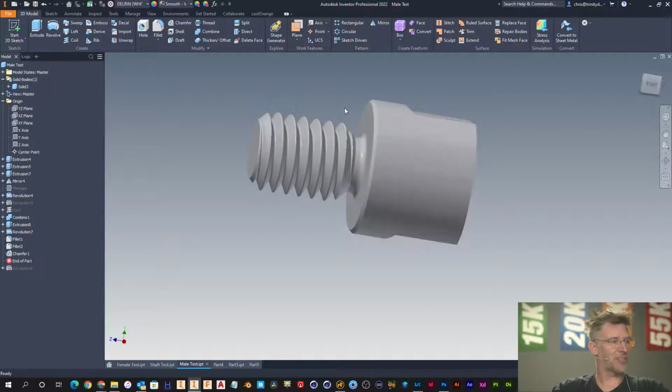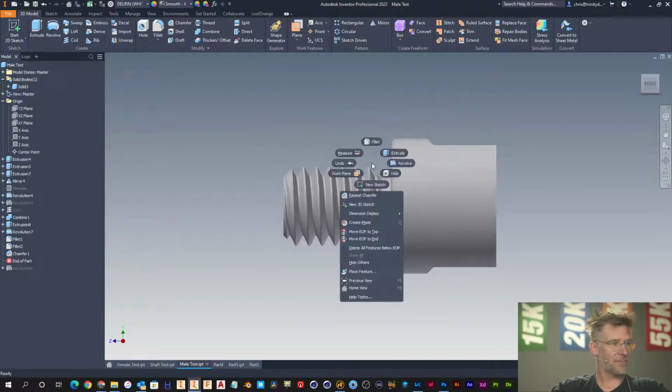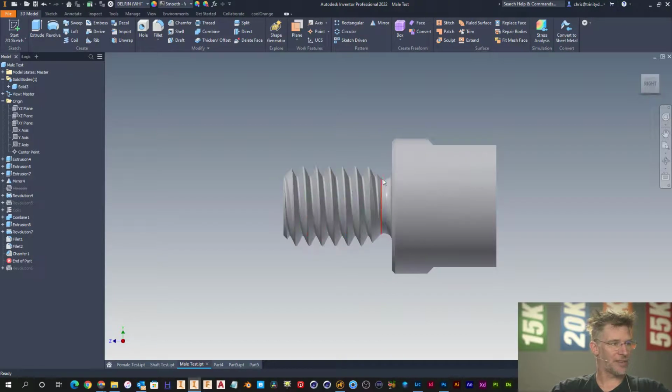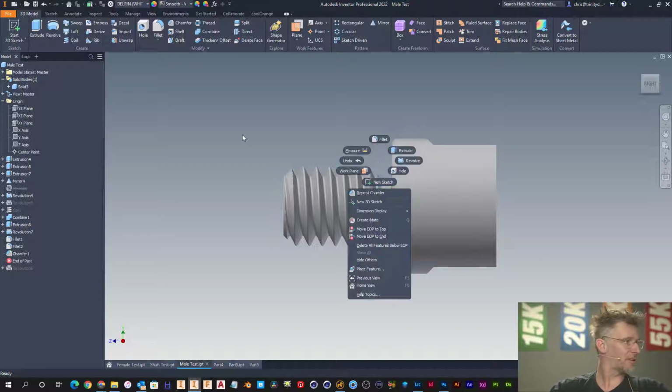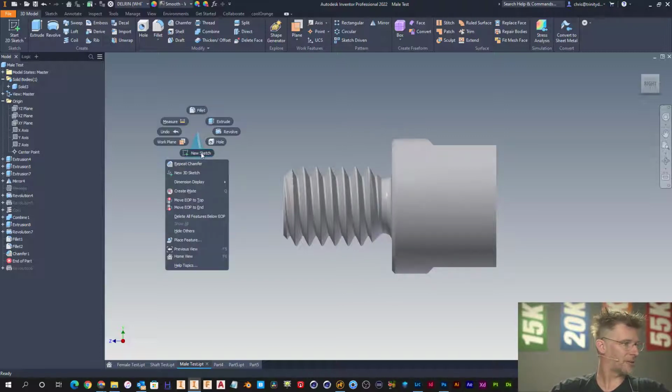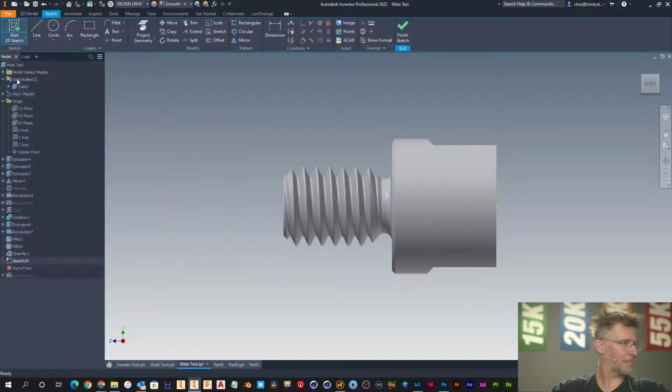And what this gives us room for later, the reason we do that relief cut is, one, it gives a way for the threads to end naturally. So they can sweep and sweep and sweep, and then right here, it's just performing basically this reverse chamfer into this nice finished cut. But two is if I wanted to do another solid on here for like an O-ring,